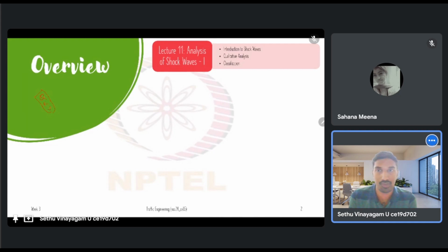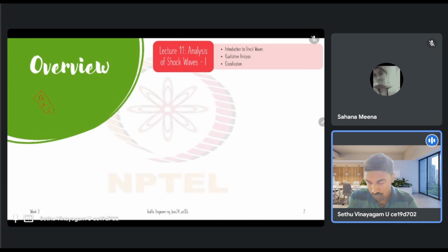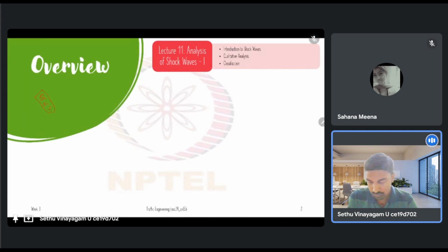For example, when we observe jam density, that's one particular traffic state when the flow is zero and speed is zero, and we have the maximum density. That's one traffic condition that we observe on the road. So that's called the jam density. Similarly, any combination of these three variables will define a particular traffic state. So you don't even need three. Any two would suffice.